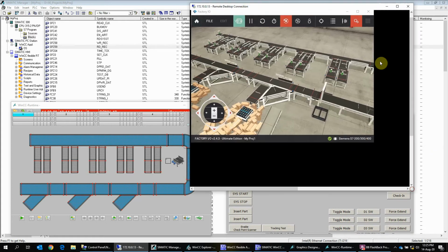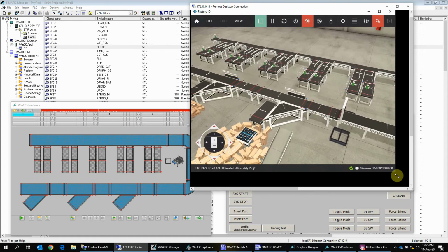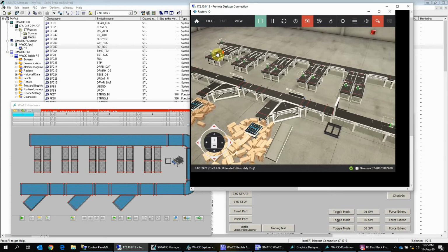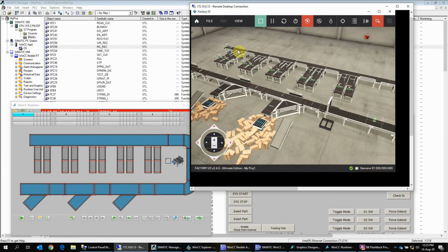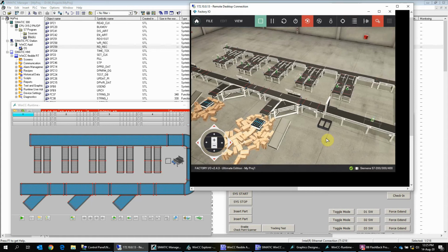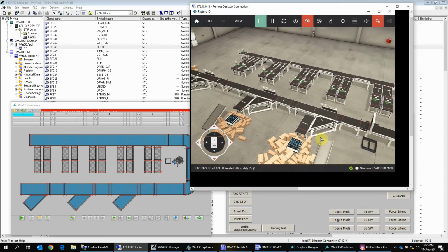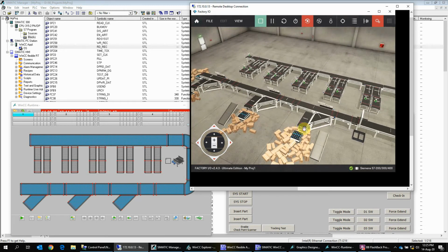Okay, today what we have here, as you can see on my screen, is a so-called conveyor layout. I have created, like in an airport, a check-in counter here. I have 10 check-in counters and a takeaway conveyor here. Along the way, I have the curve conveyor and the straight conveyor, and I also added some diverters and a so-called super conveyor here as well to do some kind of sorting function.